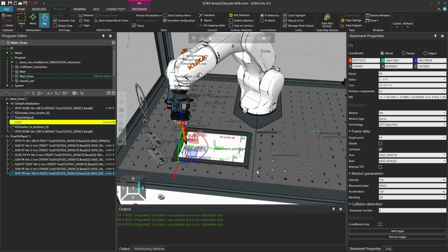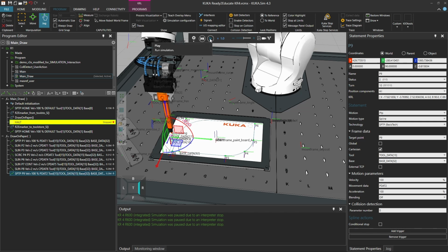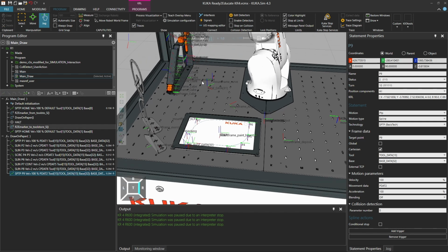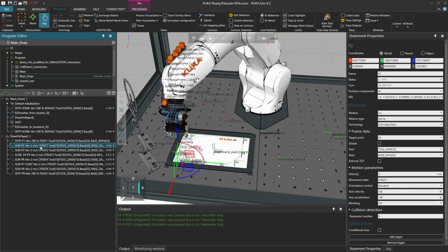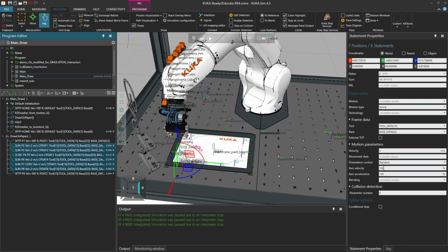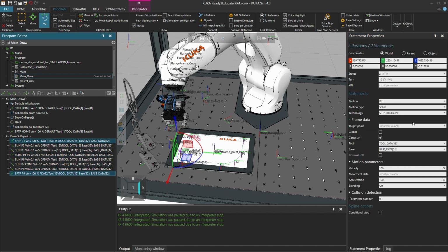Okay. The robot does exactly what it should do and does this motion, and now I just press play again and it will bring back the pen and let it fall down to the floor. But this is not too important. What is more important to us right now is actually to adapt the speeds a little bit, because if the robot goes over this whole motion at that speed, it will probably break the marker. So I'm just going to select all my points and reduce the speed to about 0.1 seconds, and also reduce the speed of this PTP movement maybe to 50%.